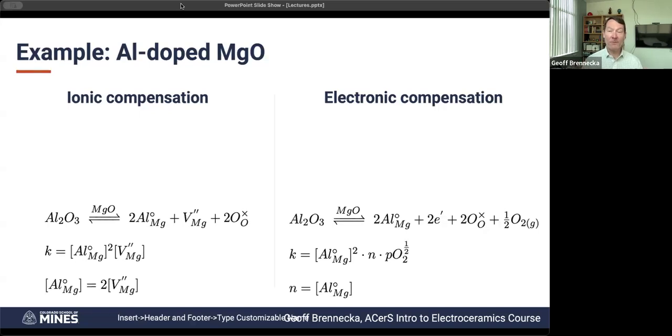Quenching is a relative term. So quenching really just means you cool this down. The concept is you equilibrate at a certain temperature, at high temperature of some sort, and then you cool it fast enough that whatever reaction you're talking about can't happen. So the kinetics determine how fast that quench rate has to be. Maybe that quench rate is you pull it out of the furnace and shove it into water, and that's quenching.